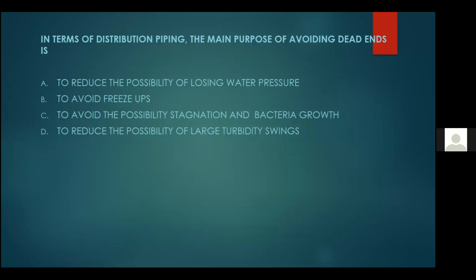If you do have dead ends, then you need a program in place to make sure that you're flushing or keeping tabs on your water quality. I would always be checking your dead end mains, because if there is going to be bacteria growth in there or something else happening, you need to flush that area and keep that water fresh. Your biggest problem out there in the distribution world is a large main with very little usage on it. It provides a lot of headaches for taste and odors and color and bacteria growth. So we've got to make sure that we're always on it.